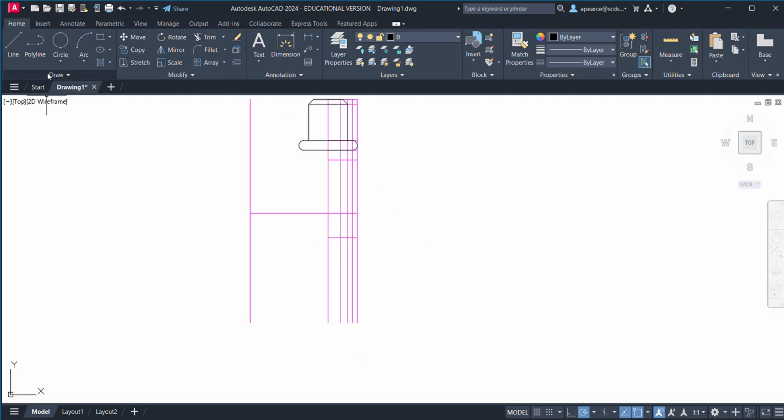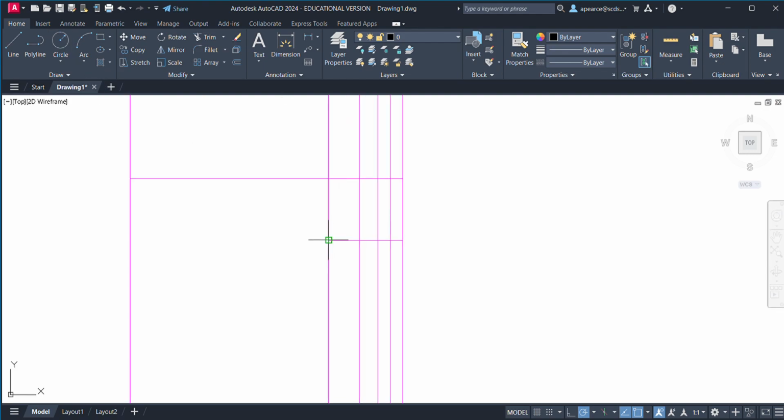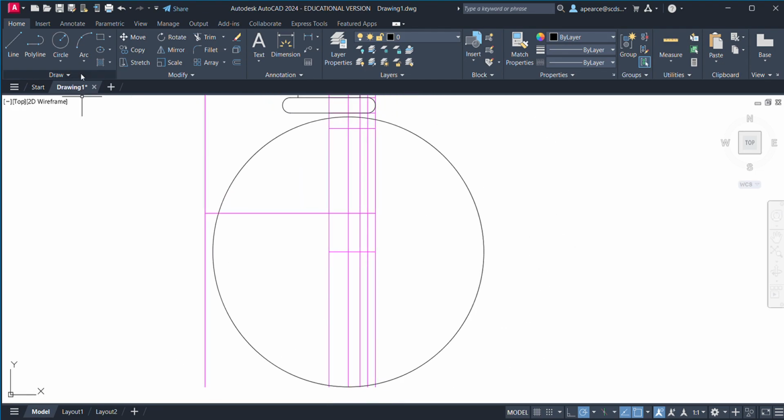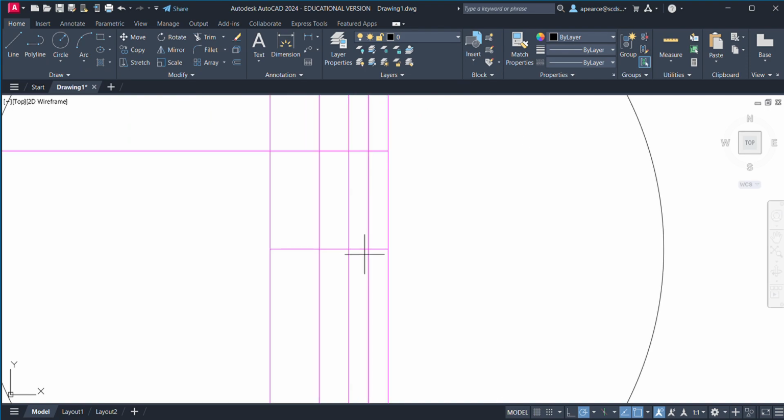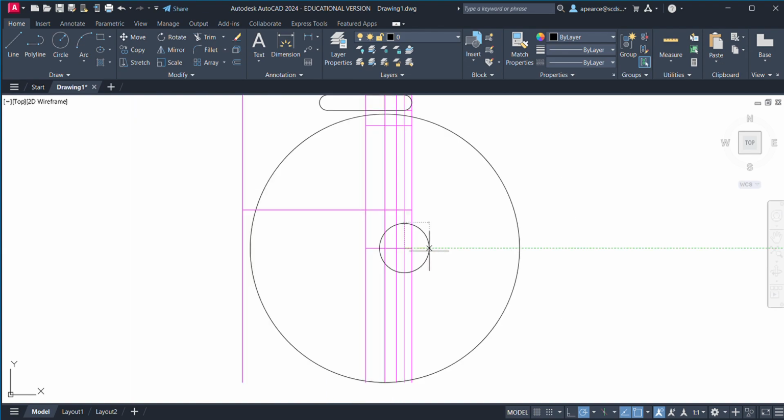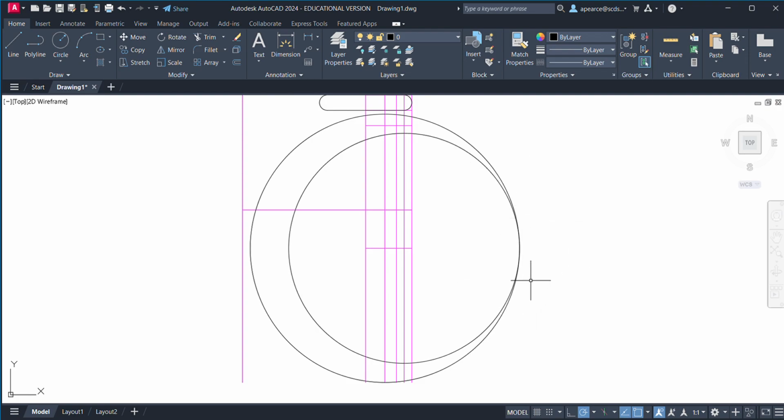The first circle is a center radius, and it actually comes down here, but then in 5 right here. And this radius is 35. And then we're going to do another circle center radius, but this one is actually located 5 more past. So it's not this one, it's actually this one. And this one has a radius of 30. And you can see how the two circles intersect.